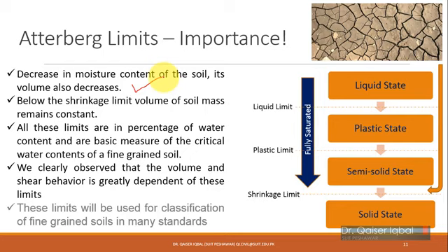In many cases you have seen that you place some mortar or some soil with very high moisture content, and when it becomes dry, it develops cracks, because with reducing moisture, the volume of that material has reduced as well, because it was in liquid state while you were placing it. Even in case of cement, if you put too much water in it and place it like a slurry, you will see when it dries, it will develop cracks. So it is very important to know that if you are placing a soil at liquid limit, it will change its volume a lot upon drying.